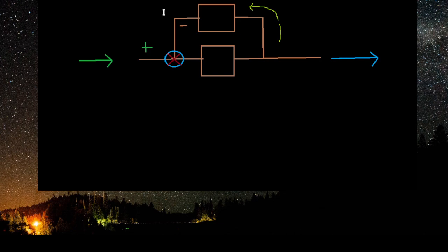So they're going over some things here in the book. They get a little bit more detailed towards the middle of the book here. So this could represent an operational amplifier. The op amp could be on the bottom, or the transistor could be on the bottom. And there's a feedback from the output of the op amp back to the input. Now, if the feedback is not correct, what can happen is it can oscillate.